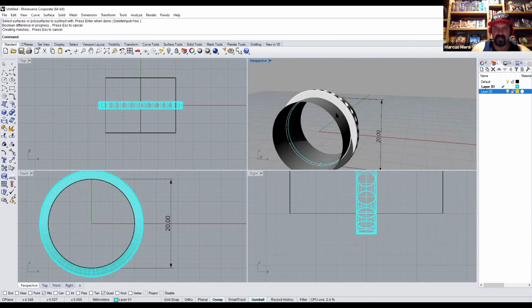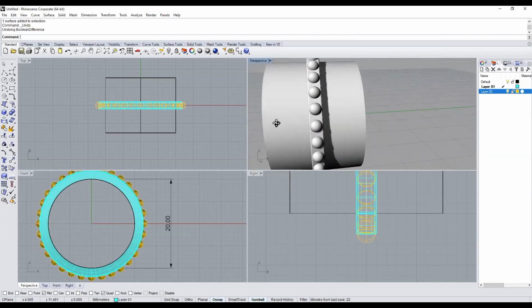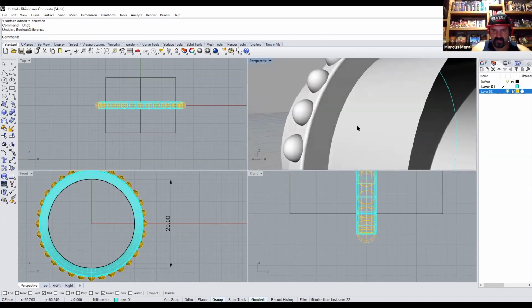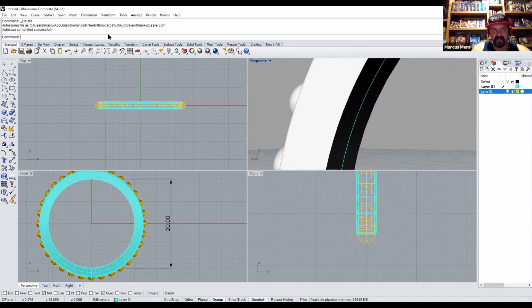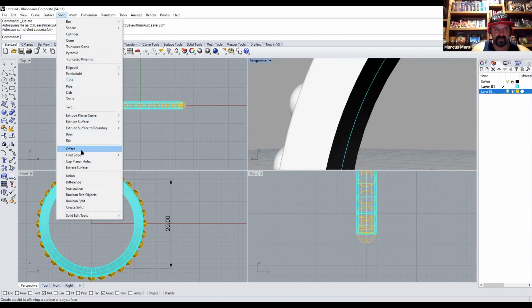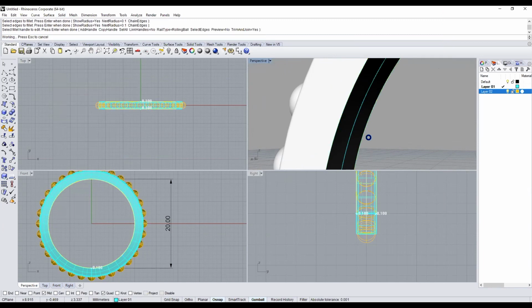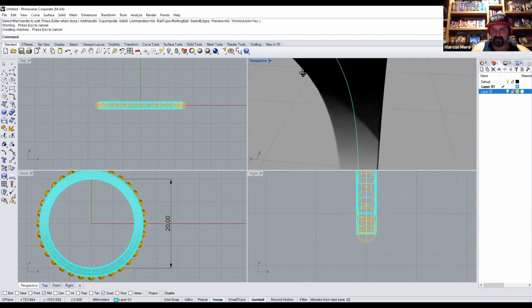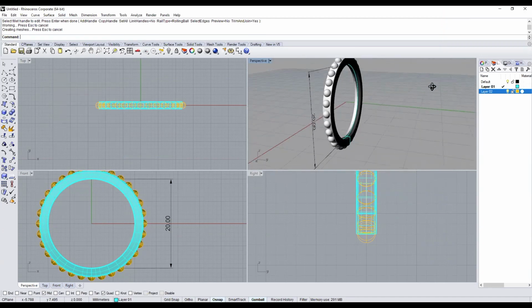Whenever you do castings, you never want to have sharp edges, or as few sharp edges as possible. You can see the sharp edge over here. I would try to fillet that as well. So you go in there, fillet, and at worst you go at minimum 0.1, and then you just choose those edges, right click, and that's better for casting.